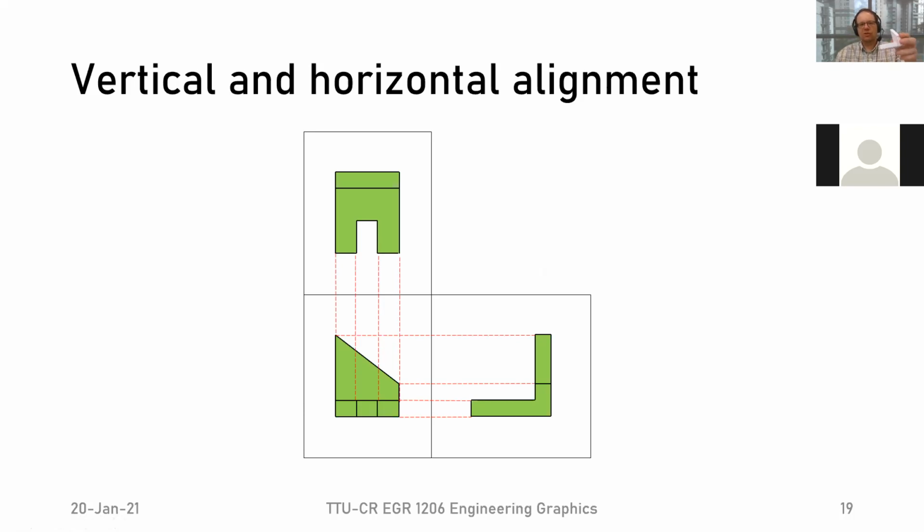Right? But again, the locations that we see here, the location of these two side pieces, if I do my turn for my glass box, doesn't matter if I'm looking from this direction or from that direction, the location has to be the same. That's why we have these straight dashed lines. So when we have our three standard projections, they always have to line up this way.